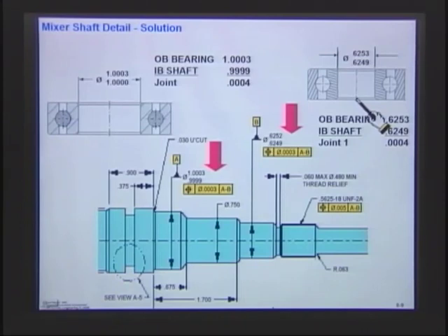When I take a look at both of them, I put the bearing up over here. Now you have all of these drawings in your workbook, so they're probably not laid out as nicely as I have them here, but you should be able to go through that pack of drawings and find these numbers. This was our bearing diameter, and remember we were looking for this fit over here. So I took a look at the relationship between this bearing, the top bearing, the shaft diameter, and then the hole here.